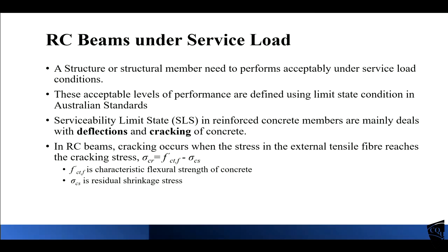Okay, serviceability limit state. What do you mean by the serviceability limit state? We are doing checks. We make sure our beam performs okay under service load. So what are the checks? In concrete, we are checking deflection and cracks. These are the two main checks for concrete structures.